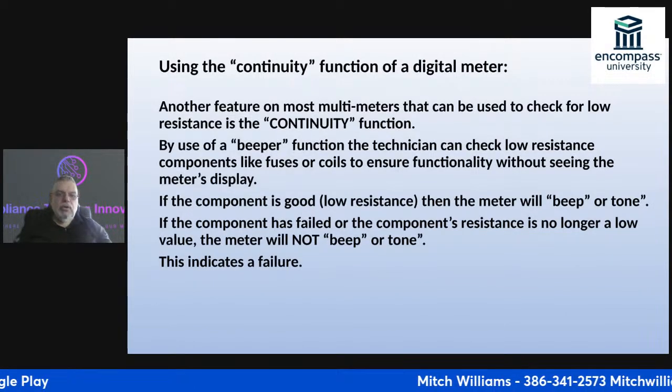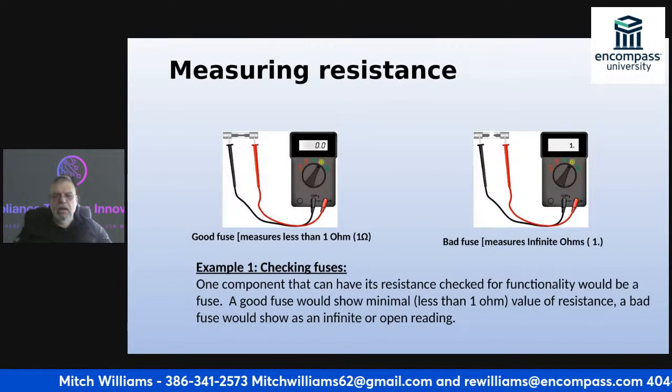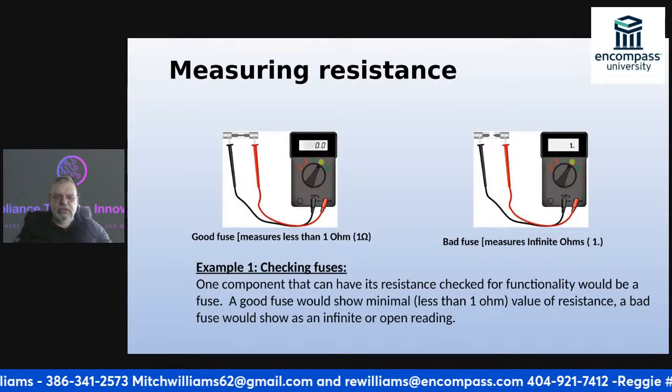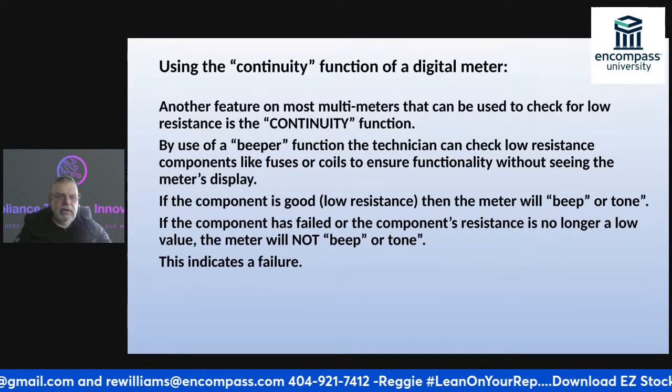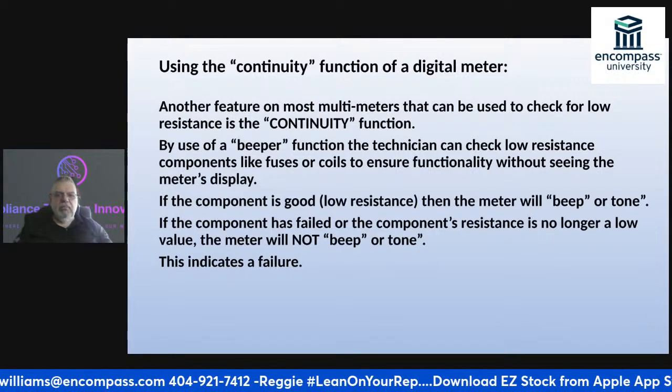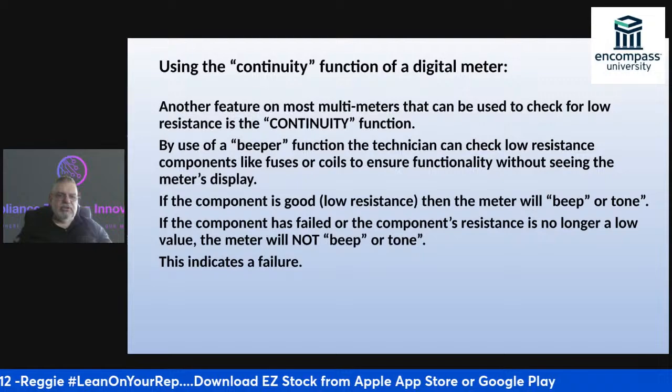Using the continuity function, we're still talking about resistance. Continuity is another word for it. Another feature on most multimeters can be used to check for low resistance, the continuity function.